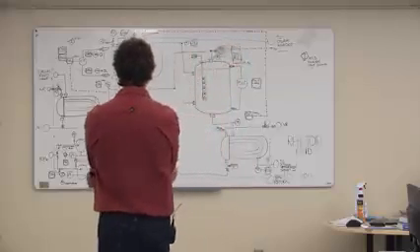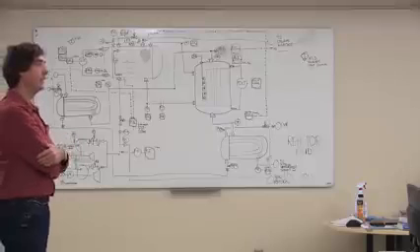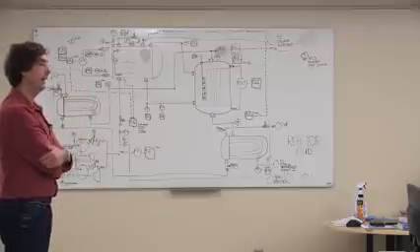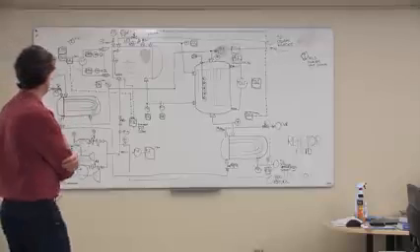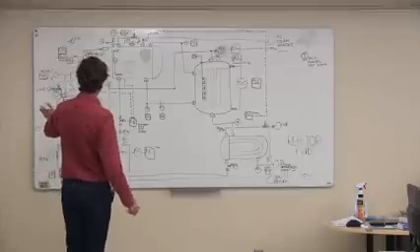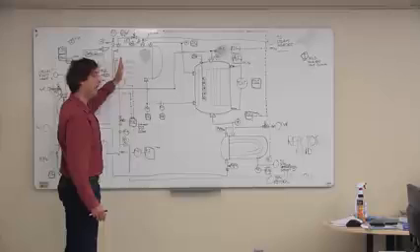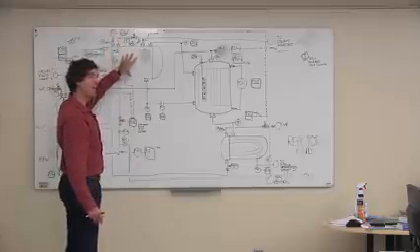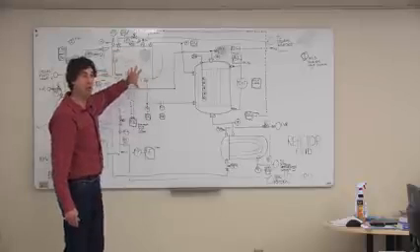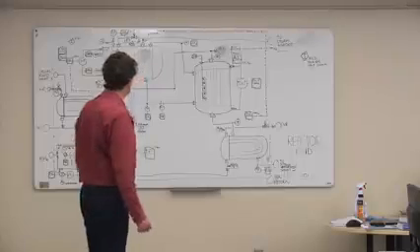Yeah, that boiler feed water is going to have lots of chemical treatment in it, but no matter what, you still potentially have some scaling and some solids build up and things like that. You can't possibly have completely pure water. We're basically going to pour thousands of pounds of water in here per hour. We're going to boil it out as steam, and we're going to be left with the solids that came in with that. So even if there's parts per million of solids, that's going to build up over time. That's going to be a problem. So what do we do about it?